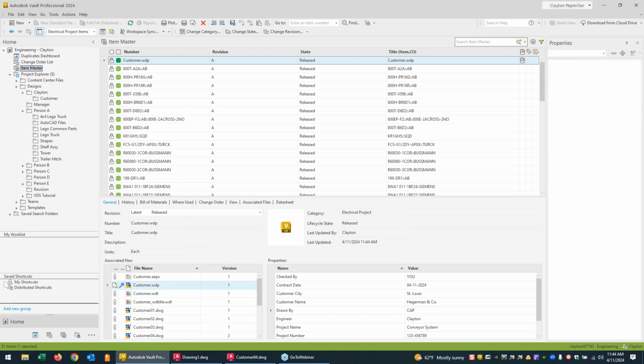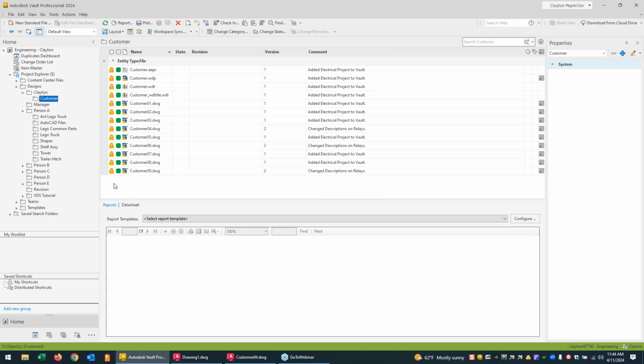to basically lock down the items, the bill of materials, and over on the drawing side, it's going to lock down all the drawings. A lot of people question drawing lockdown, but think about this. If somebody opened a drawing and added a bunch of push buttons and lights to it, is your bill of material accurate? No, you're changing drawings outside of your official bill of materials. So in order to keep everything on the same page, we release it into a lockdown state. Again, the Vault is a lot about drawing protection.